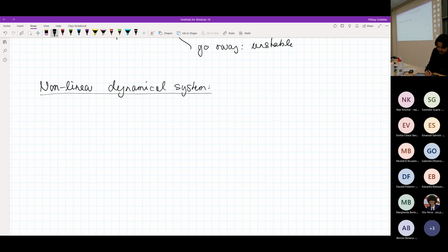Well, the easiest way to write that is dq/dt is some f, which depends on the state q and some perturbation or bifurcation parameter, which I can call the Reynolds number in my case. So the q here would be what in dynamical system theory is typically the state, or the state vector. That just describes how my system looks. That could be the velocities, for instance. So my velocity field could be the state of the system at a specific point in time.